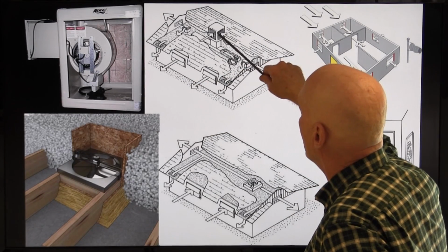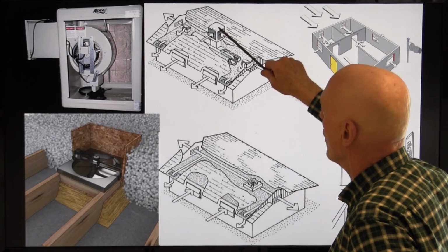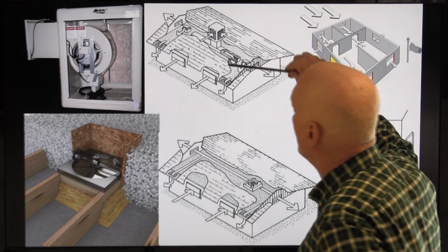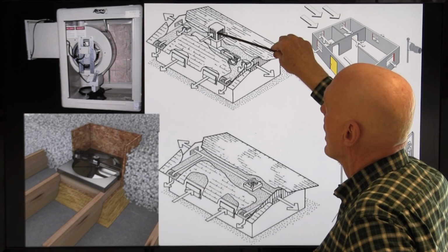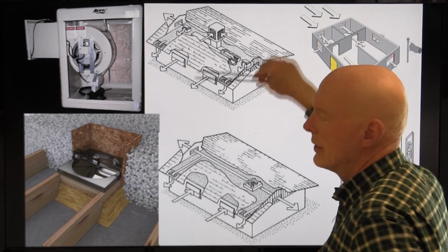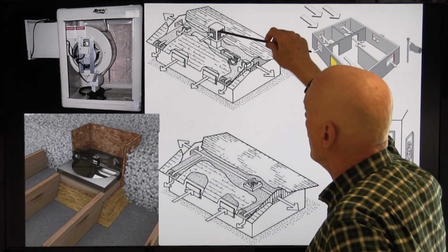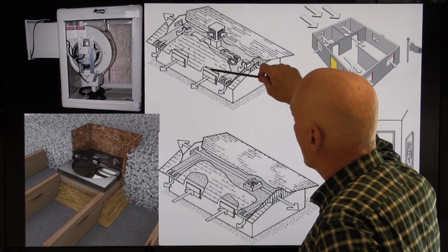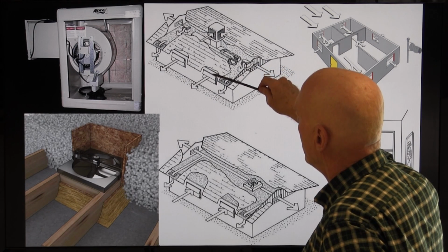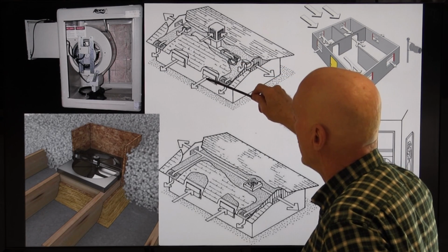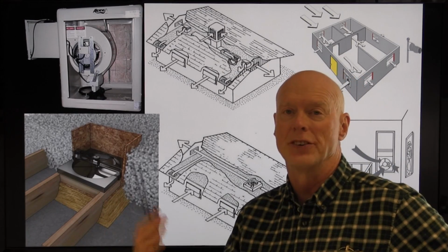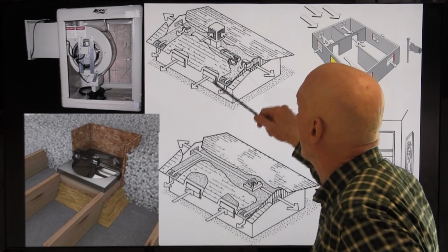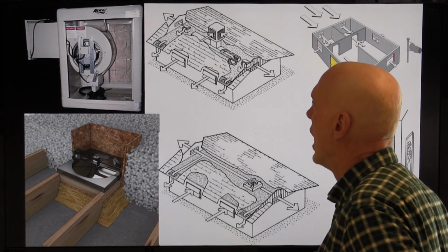So we have our evaporative cooler here on the roof or alongside of the house or near a window. So we bring hot air into the evaporative cooler. It gets humidified, which drops its temperature. We bring the lower temperature air into the home or building, and then we have open windows and the air is forced out. So you have this constant circulation of fresh, low temperature air. This works well in dry climates.